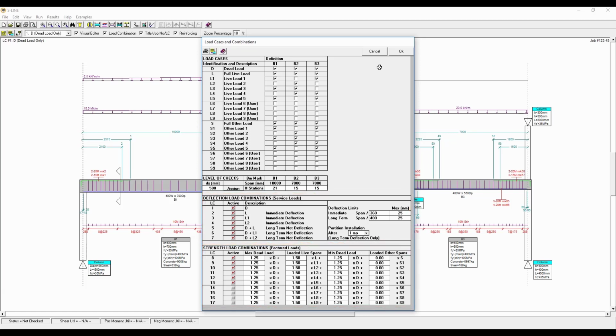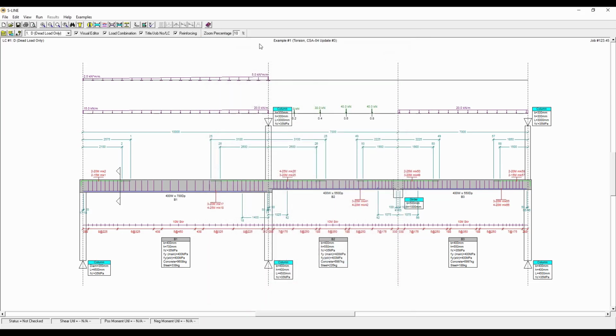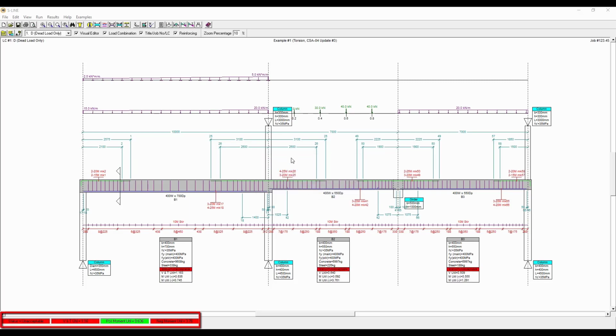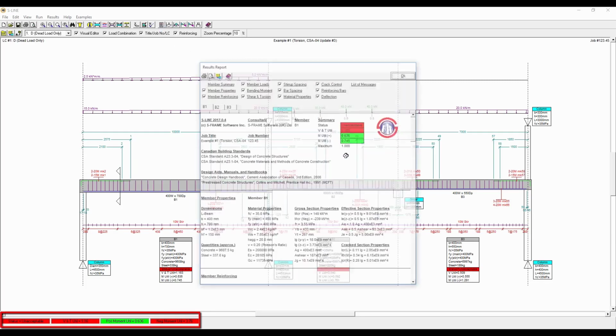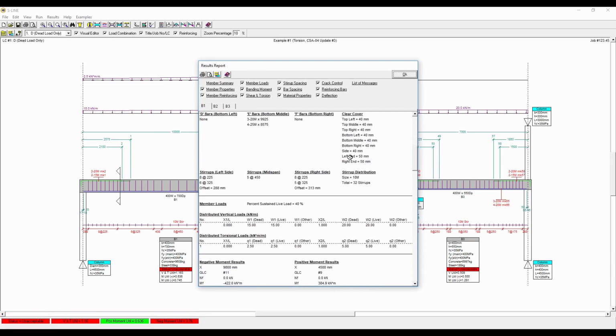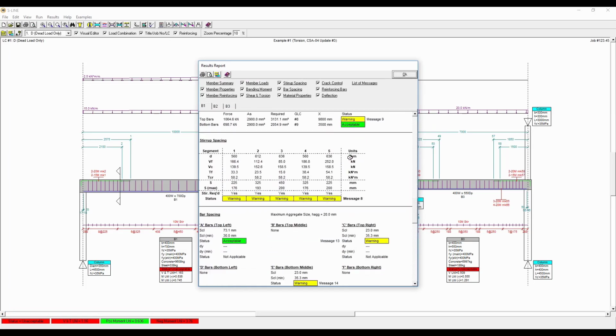You have full control over the auto-generated data, and you can always edit and overwrite it, or create your own load cases and combinations based on your specific needs. You can then perform a code check and review the detailed report, which includes information on the various checks and references to design code clauses for each bay.